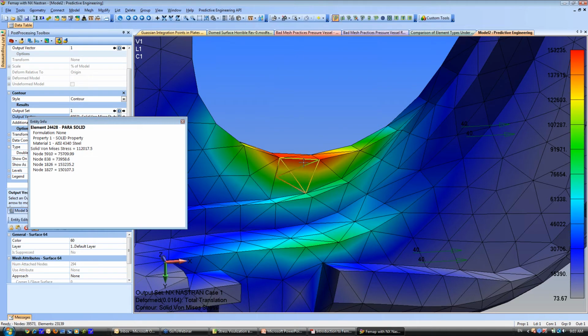But I really prefer to keep it simpler, and I look at the element shape, and if it looks pretty close to 1 by 1, or 1 by 2 by 1, or 0.5 by 2, there's reasonable limits, but it looks pretty regular. And then I look at the contours, and it looks pretty smooth. It doesn't look too jaggy. You would say the stresses are pretty reasonable, 10, 15% close.